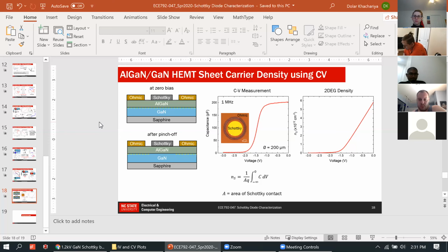And so maybe to go a little step further, if the gate current starts to approach the same order of magnitude as the drain current, then you know that there's some additional things going on in terms of current flow within the device, right? In an ideal transistor, a MOSFET for example, that we assume from silicon, we usually assume that gate current is ideally nothing, and it's only current flowing across the channel. But in a Schottky diode, we know that if you apply a large enough forward voltage, you will get pretty significant current. We just saw that with the exponential relationship. So in a D-mode HEMT, you might see something like that as well, and it might impact your drain current behavior as well.